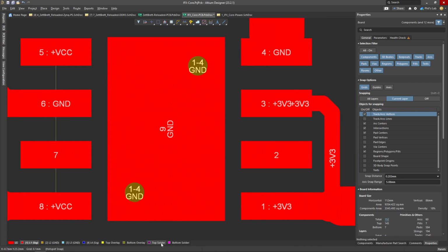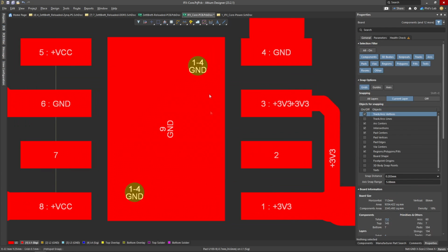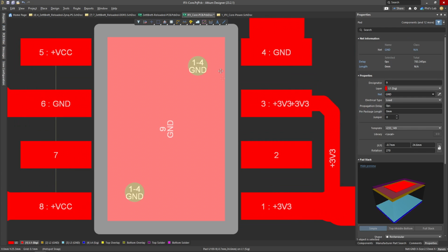What we also could do is maybe adjust our solder mask layer, so actually only part of the thermal pad is exposed, but then again, that might also hinder the thermal properties a tiny bit. Again, it's a bit of a compromise. And it's also good to ask your manufacturer what they prefer and if they'll have any assembly problems with having these vias in this pad, and if there's any cost adder.